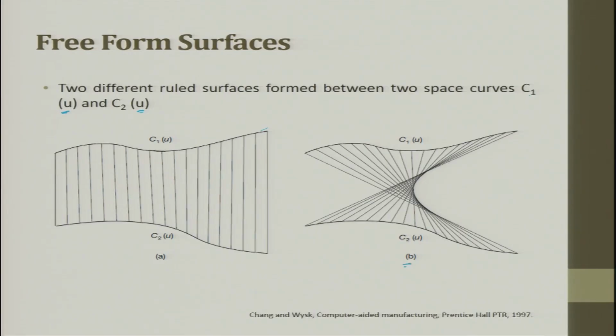With the same two curves, the way you specify them, you can generate two different surfaces. Next, these are three different ruled surfaces: planar surface, cylindrical surface and conical surface. Different ruled surfaces are obtained from the same closed curve; the different surface results because of the difference in the selection of the start point on each side of the curve.